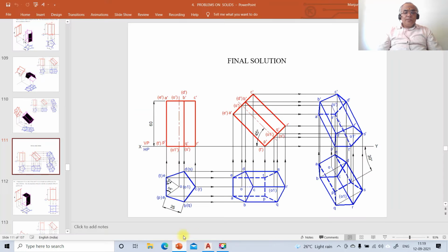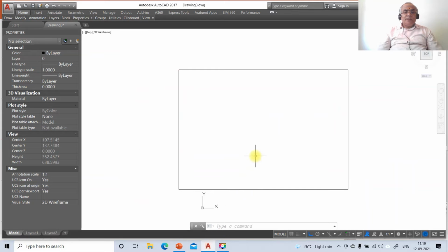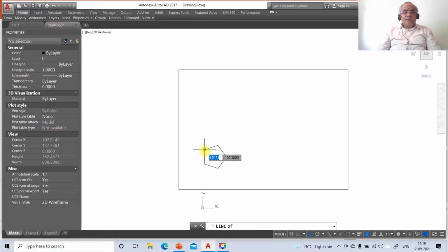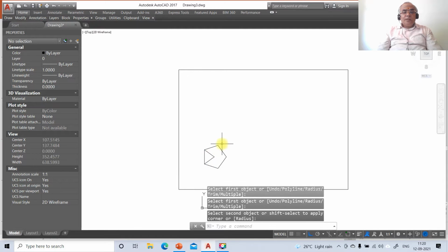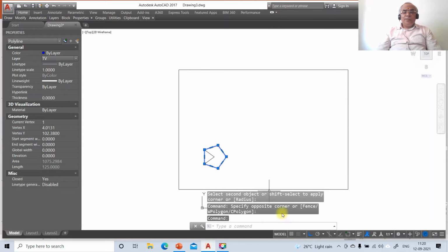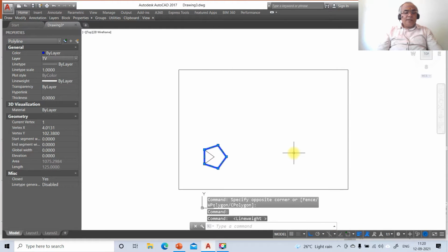Now we go for the polygon command, take the distance as 25. So go to polygon, take the number of sides as 5. Select the edge option, take this here, type 25, then go to line, take INT of this, draw midpoint of this. Take a line, take INT of this and draw midpoint of this. Now once you have this, go to fill in between these two, click over this, go to layer, make that layer as top view and switch on the line weight display.